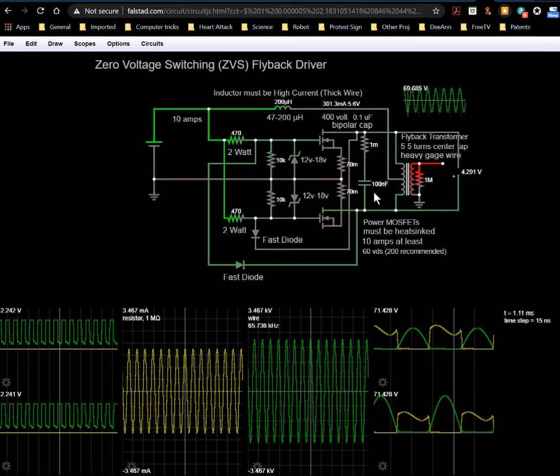But what's happening is, if we charge our inductor up with this current, that'll form double the voltage across it. Once the thing's charged up and the transistors change state, it starts to oscillate, and it oscillates by taking the energy stored in this magnetic field and forming a voltage across it, so it tries to maintain its current flow.